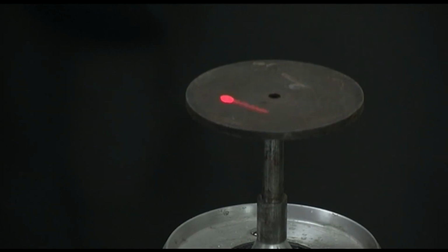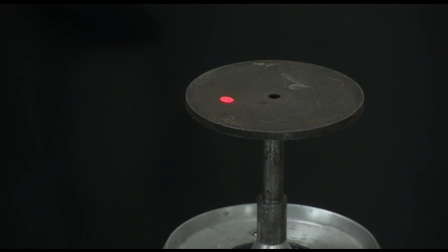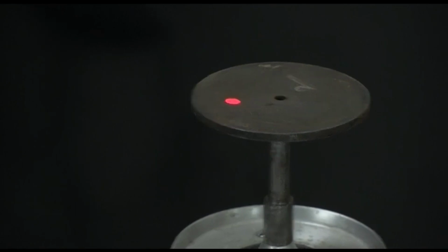The reason we do not excite it at a very high frequency is that the laser does not need it. This is one of the most sophisticated lasers. Its specifications are that it is a helium neon laser, and it works with a wavelength of 633 nanometer. Its minimum detectable vibration speed is 5 micrometer per second.